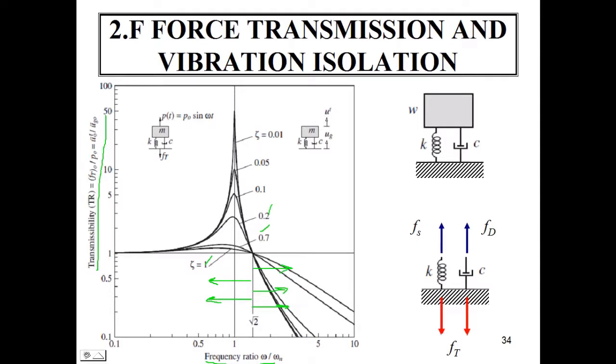Since natural frequency and stiffness of the support system are proportional, the stiffness of the support system should also be small. In this frequency range, no damping is desired in the support system because damping increases the transmitted force. This implies a trade-off between a soft spring to reduce the transmitted force and an acceptable static displacement.